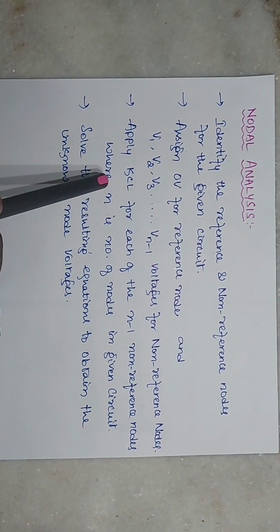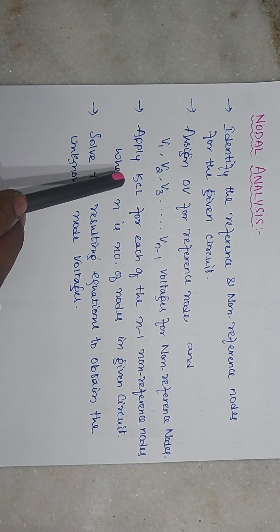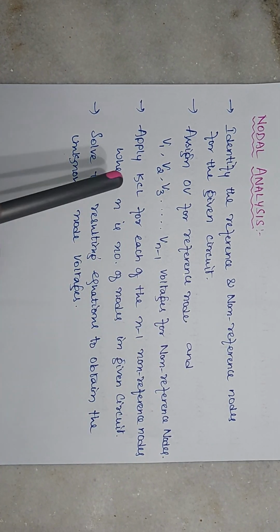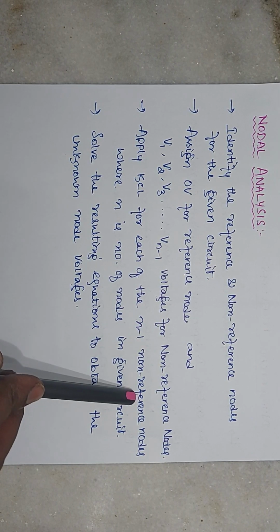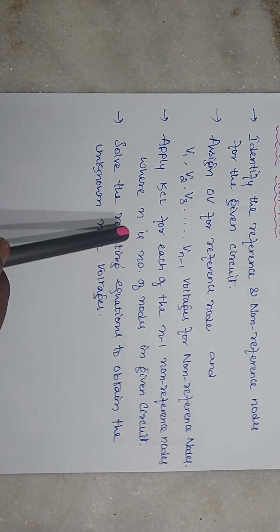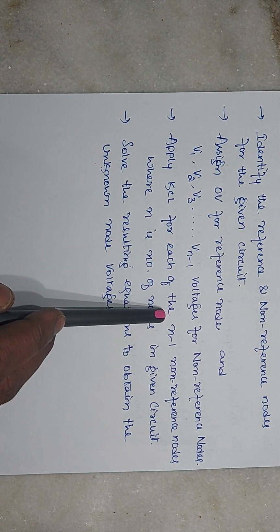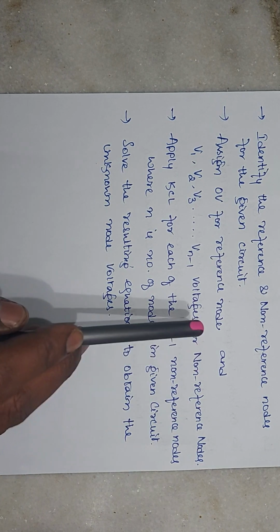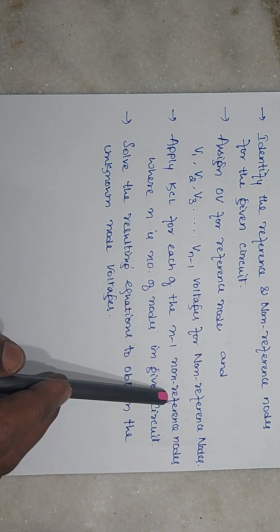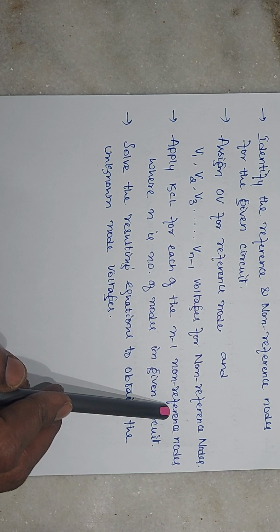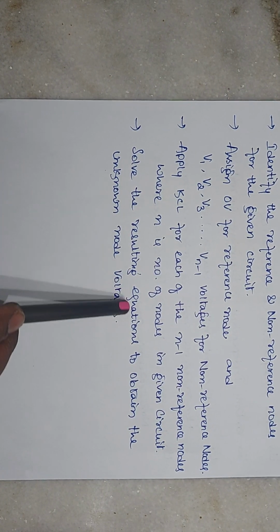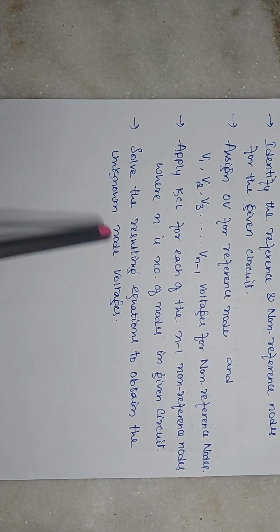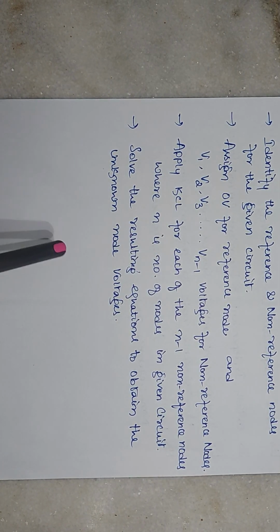After assigning this, we will apply KCL for each of the n minus 1 non-reference nodes. We have to apply KCL for the non-reference nodes only. After applying this, we get the equations for these non-reference nodes. However many non-reference nodes there are, that many equations we obtain. Solving the resulting equations to obtain the unknown node voltages is the final step of nodal analysis.